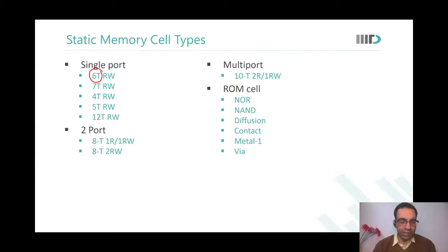So I will already prepare those bases. I will already have the wafers processed up till metal 1. As soon as the user code comes, I will generate the mask for via1 and I will process the wafers from via1 onwards after the customer places a request.